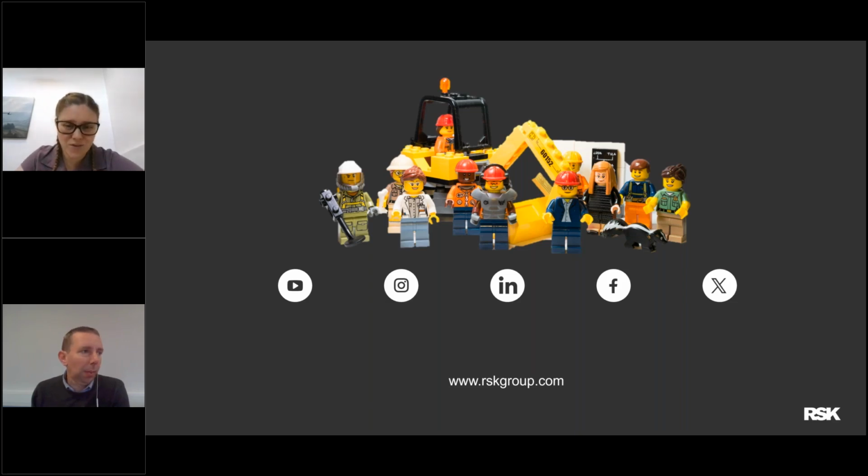Well, first, it depends on how soft they are. It might be that you can use some road plates or some big track mats to be able to get your vehicles onto site. With that being the case, you probably want to use something like a CPT rig, as this is going to give you the most data from the cone. Once you start using the percussive rigs, they're going to sink very quickly, and the data that you get is going to be a little bit meaningless, whereas the cone penetration device, depending on what types of cone you pick on the end, can give you a lot of information from very soft soil.